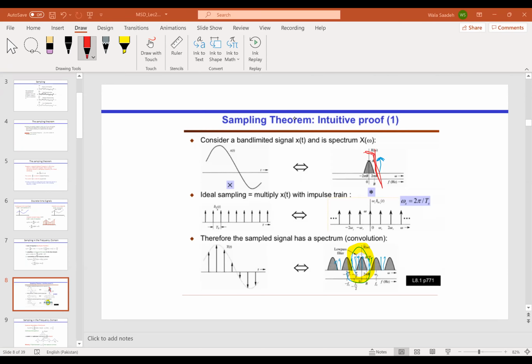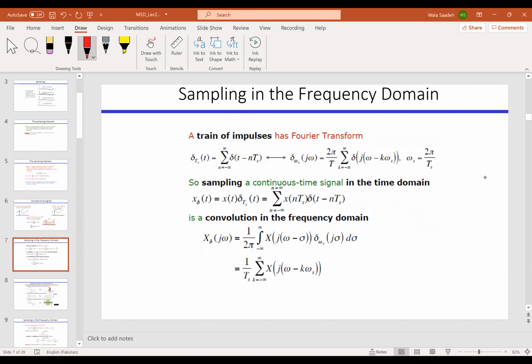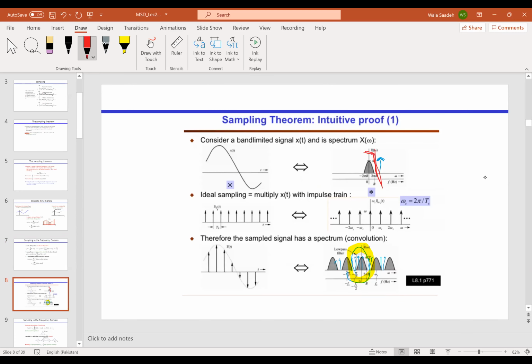After you multiply it, basically, let me go to the previous. If you look at it from the math perspective, it will again come within our band of interest. So this omega, when k is equal to 0, will come into our band of interest here. This, or the bad noise that was originally here, has now come on top of my original signal. So I cannot differentiate them from each other afterwards. And that's something bad and undesirable. We don't want it to happen.